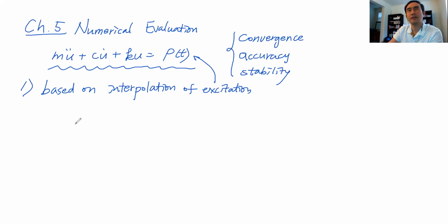So I think I explained it in the class, but this is the regular and original equation of motion. And in the earthquake engineering field, we rearrange this equation. When you divide everything by m, and then C over m and k over m, we can rearrange those terms into other parameters, which are the natural frequency and the damping ratio.